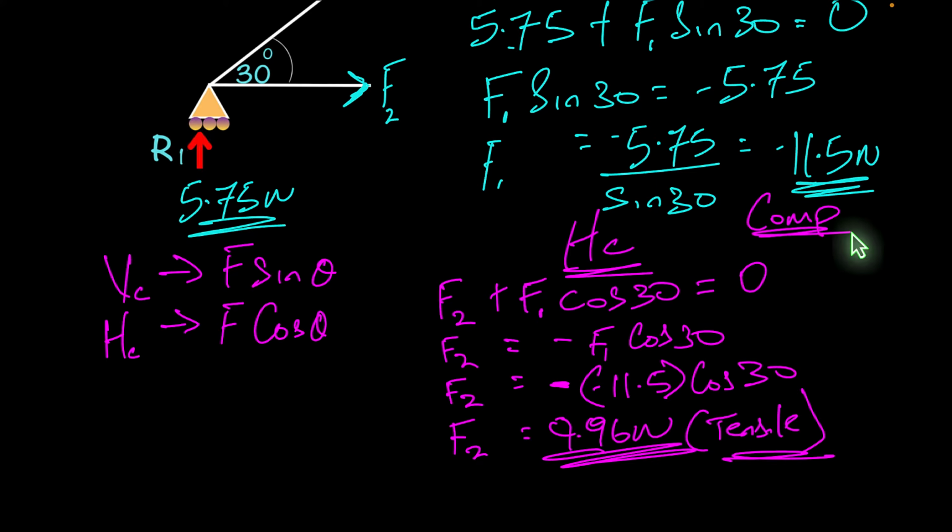So that's joint 1 done, and we're going to go to joint 2 now to calculate the internal forces. For joint 2, it's going to be the same principle we follow. So let's start by assuming that our arrows are pointing away from the joint, meaning they're all tensile members, and then when we get our answers, we'll prove whether or not they are.